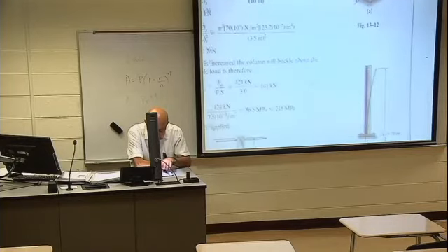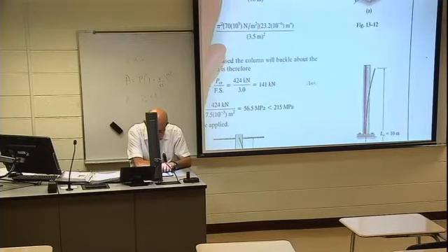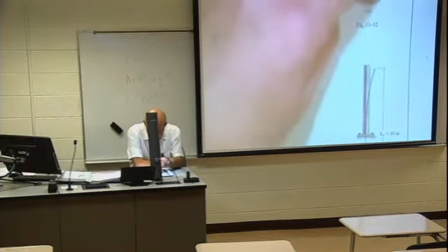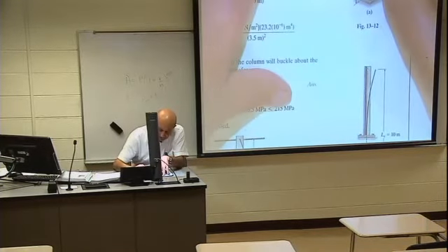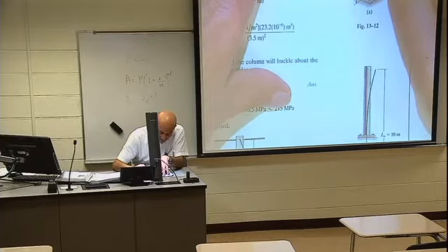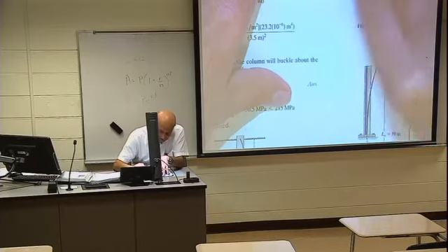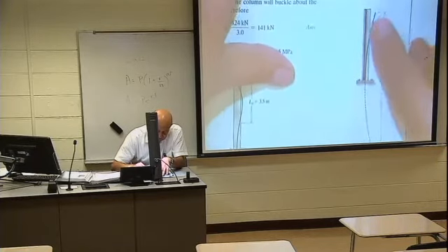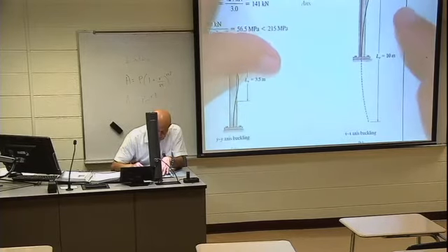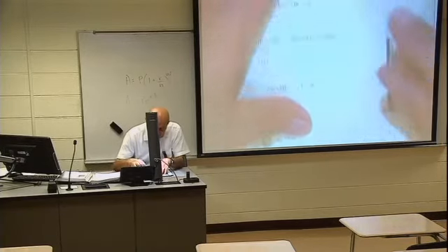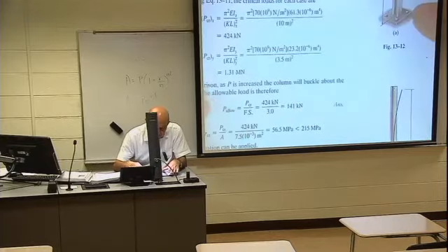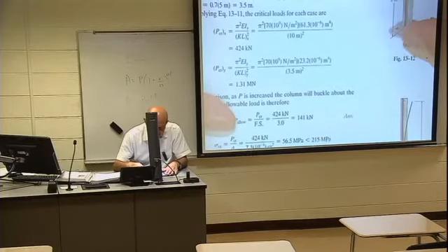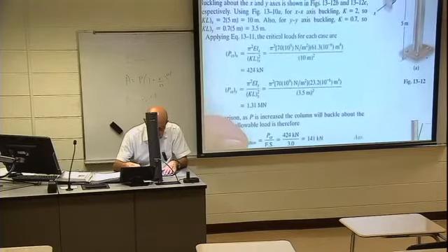So now look, please. Buckling with respect to y-axis, okay? So pay attention, this beam or this bar can move along this cable. So it can move in this direction along this cable. So that will be the buckling mechanism. So that means that effective length is twice this length. Where is this length? So let us have a look here.